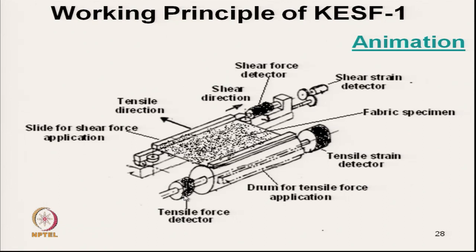As the drum rotates, it will extend and stretch the fabric, and the load will be applied on the fabric specimen. The other jaw, which is connected with this slide, is for measurement of shear.